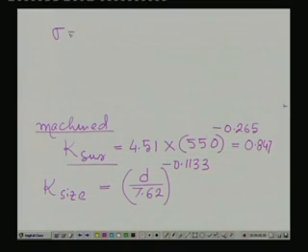Okay. What I am trying to say is that in this case we know that sigma equals M y by I, or it is given as M by Z, since I by y is Z. If we consider this equation, the M we know, and we can find the stress value.